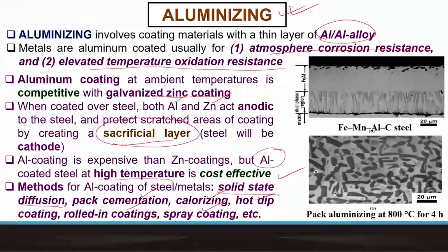It's very similar to carburizing and nitriding processes, but the only difference here is that we are talking about entirely solid state diffusion of substitutional atoms. So all these so-called magic elements that we are talking about, aluminum, silicon or chromium, are all substitutional elements in the steel matrix.